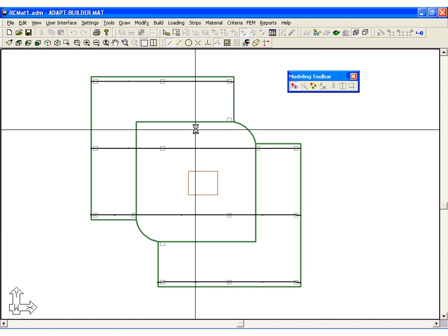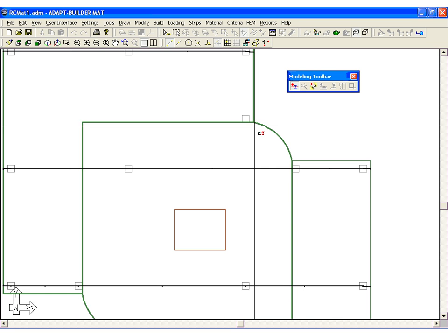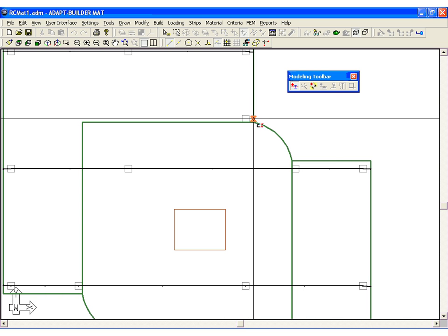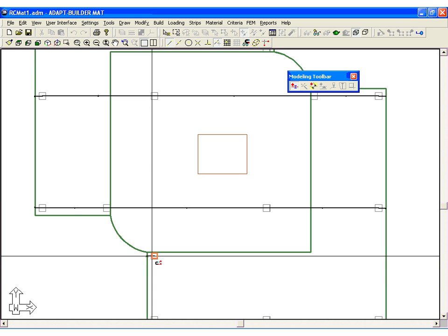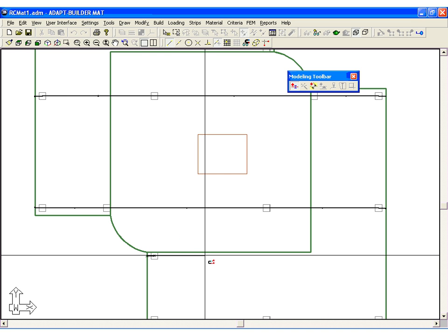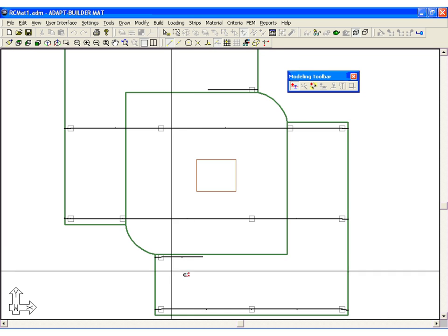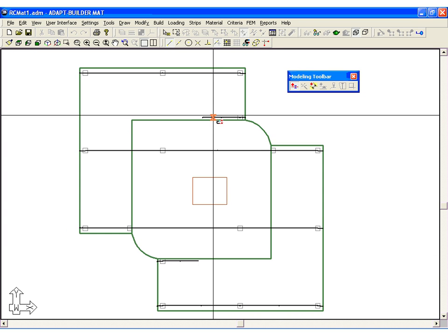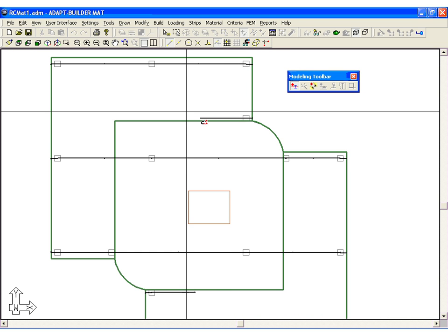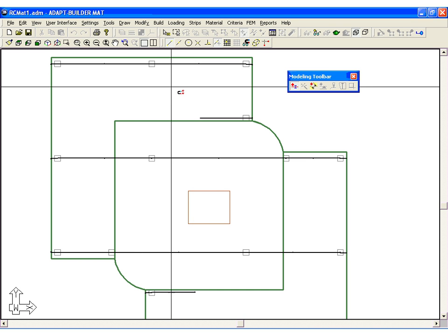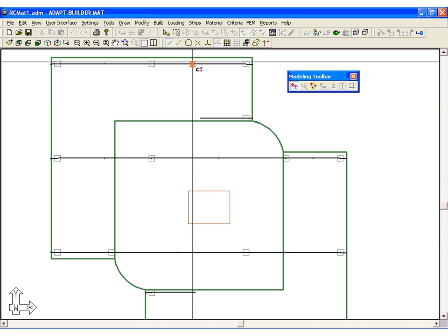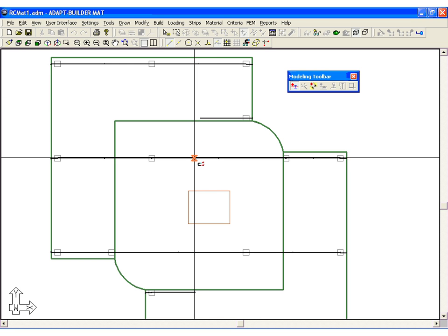For this direction, the X direction, we're going to include support lines over these columns. We're going to go to about half the span between these two columns, and we're just going to terminate the support line there. And we'll do the same in this direction. This is one option to include these columns in the design. We could ignore these columns, but then the tributary would just be between these two support lines. The program would split the design strips between this support line and this support line.